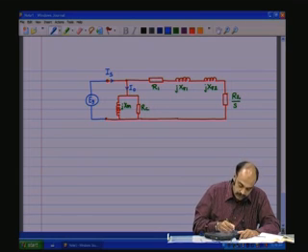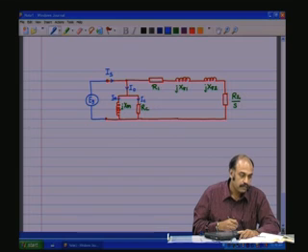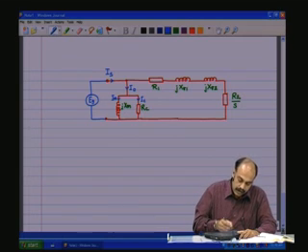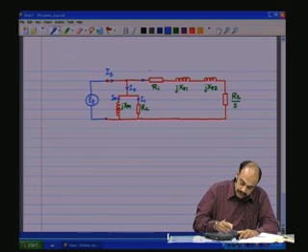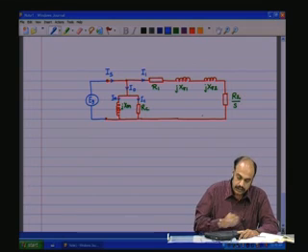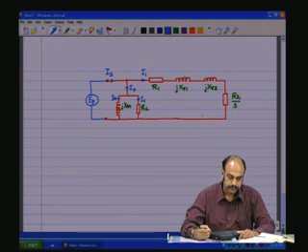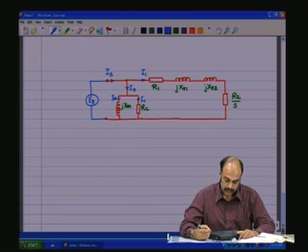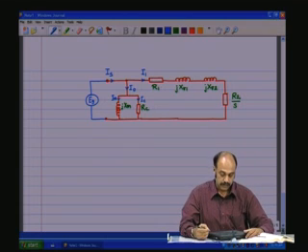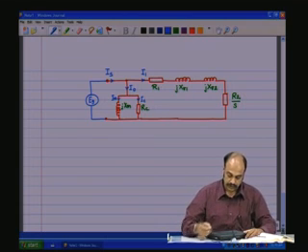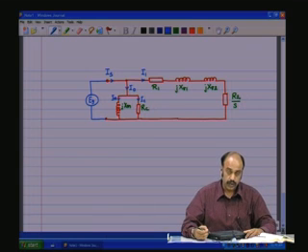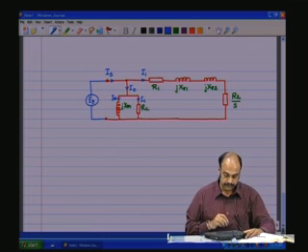So in I0 we have IM, IC, and in this you have I1 which flows through. So I1 is what is flowing through the major part of the equivalent circuit, which is the stator and the rotor equivalent brought on towards the primary side.